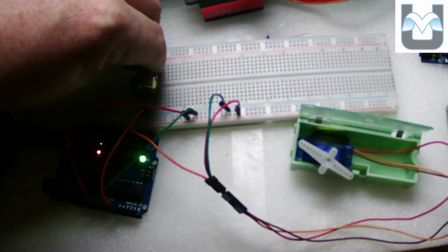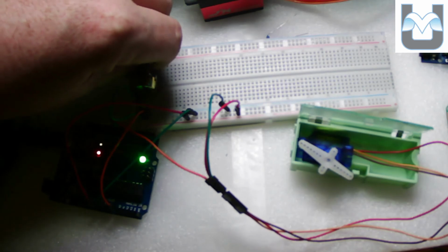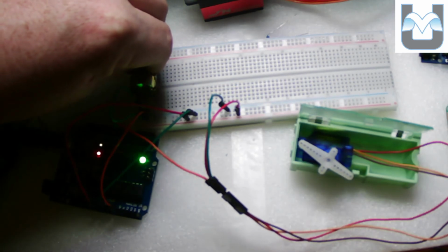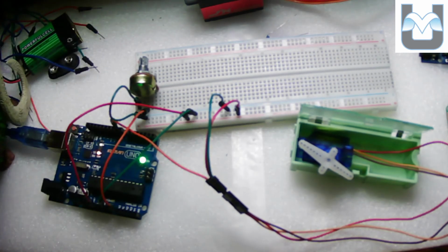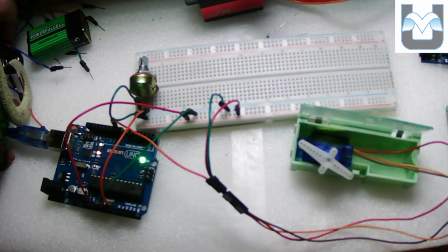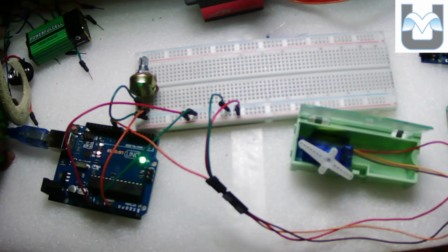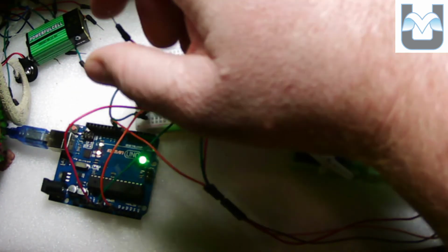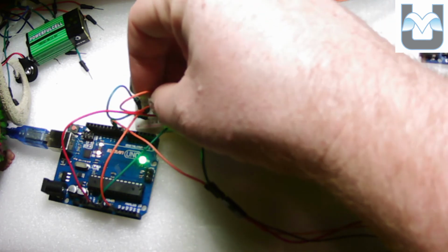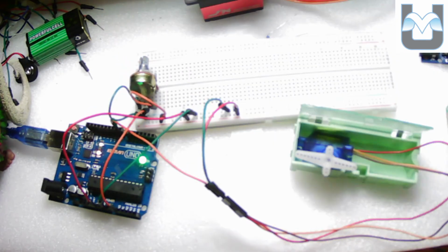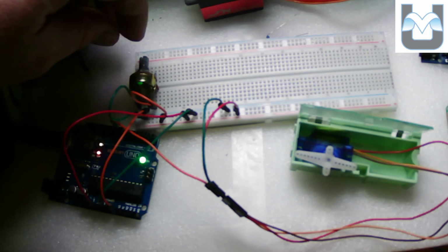I'm going to slide over here. I'm just going to spin this. Oh, what's going on here? Oh, I have a wire missing. That's unfortunate. This is part of that troubleshooting process, making sure you have a nice, easy to work with workspace. I'm just going to spike a wire very quickly into the other side of the potentiometer. That is negative, that is positive. Okay, and as you can see, the servo actually started moving there.